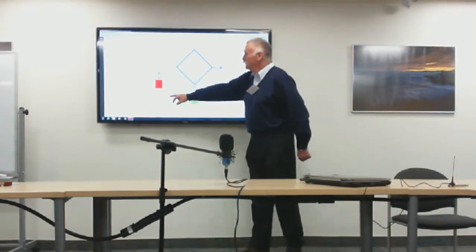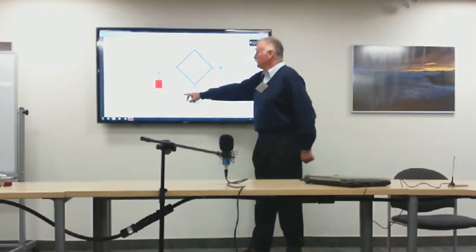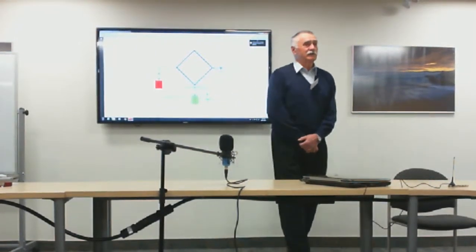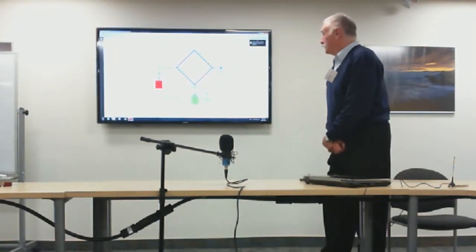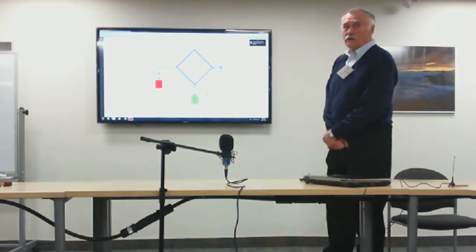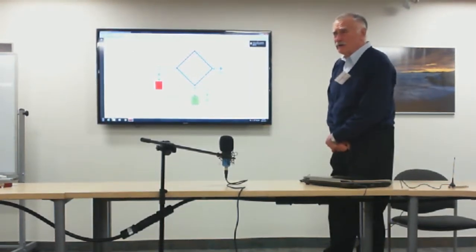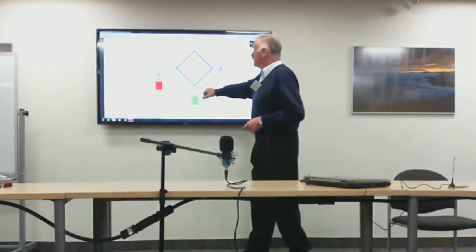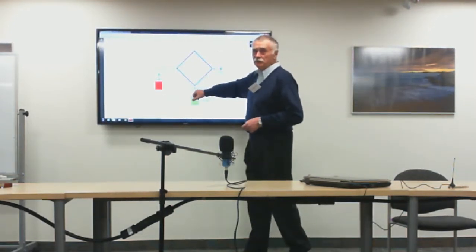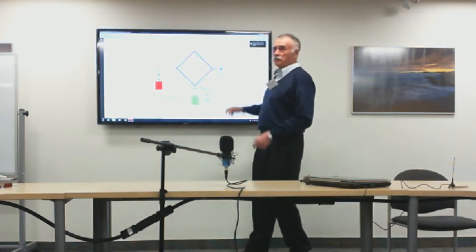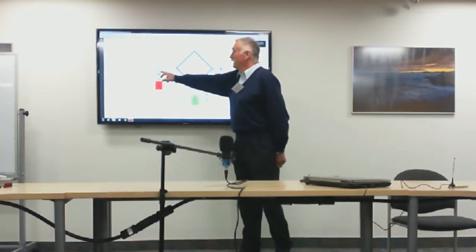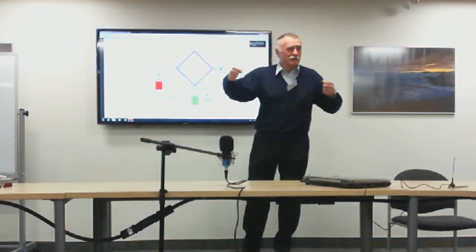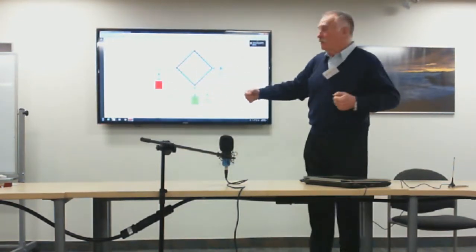We change the polarity with the negative one. The negative 12 volts goes to the anode of both diodes. So both diodes are cut off. When a diode is reverse biased and it's cut off, then you can cut it out. So this reverse biased diode over the receiver lifts the short circuit from the receiver. This reverse biased diode in series with the transmitter breaks the wire, no RF can go through.